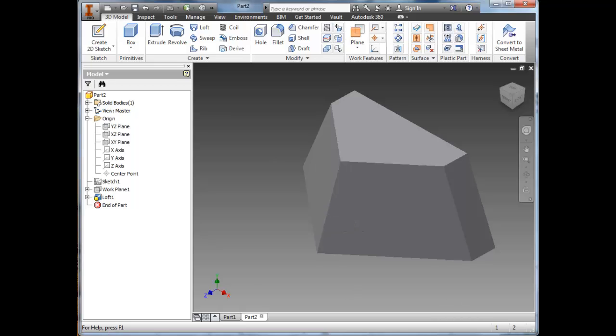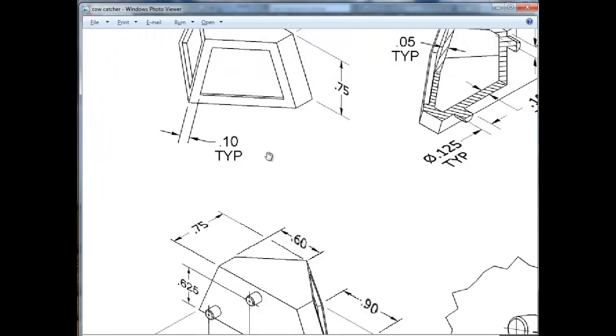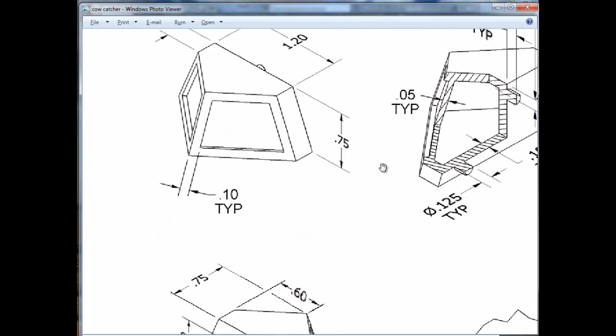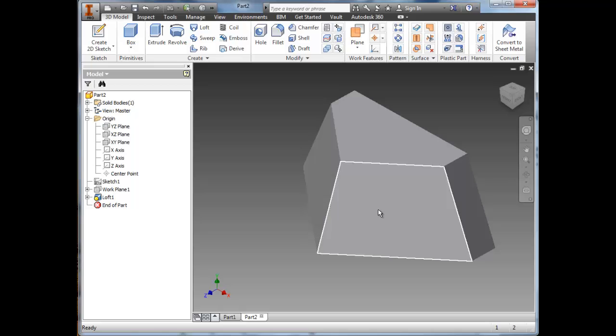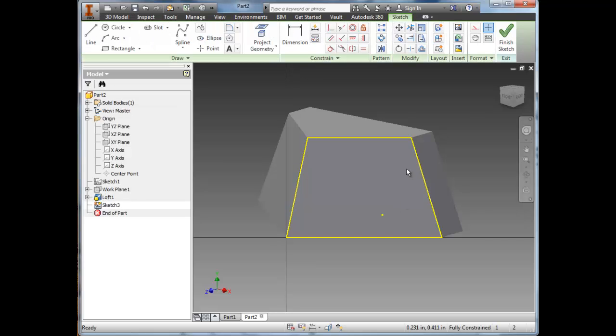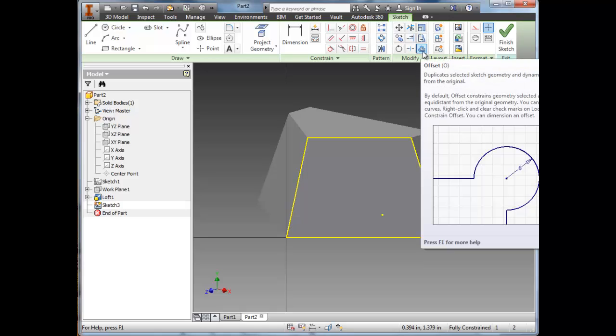We have a couple of different windows in the front. They're not all the way cut out, but they're 0.1 in on each side, and they have a depth of 0.05. So on the front, I'm going to pick one of them. It doesn't matter. I'm going to click on the front and say New Sketch. And I could just use the line tool to draw the basic shape again, but I don't have to because of this. The very last tool in your Modify